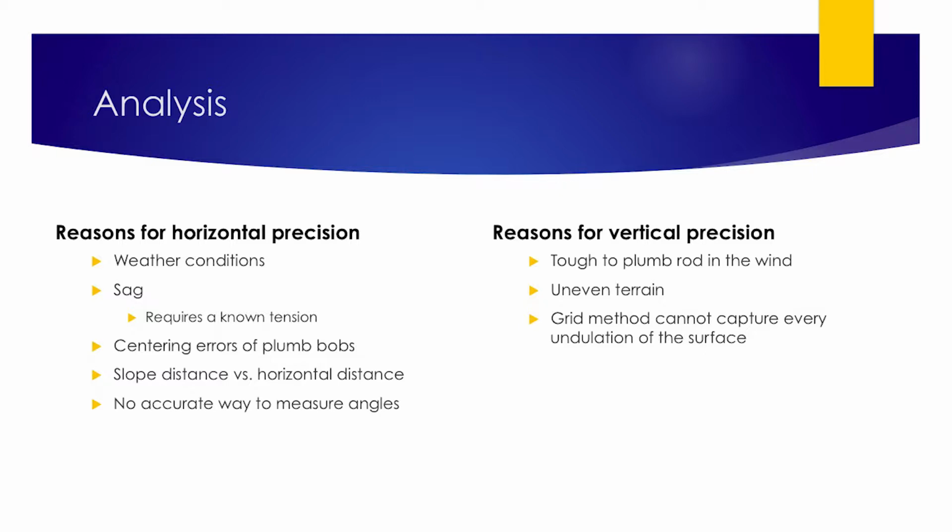horizontal distance, you know, when we have both sides pulling, at times one side would be a little higher to get it over different terrain than the other side. So instead of getting that exact horizontal line, we were actually getting a slope distance line. And we didn't use angles. We actually held distance measurements over angles.